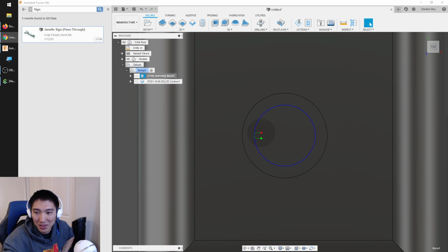Can you use grinding bits in the Nomad? Technically, you can, but you'd have to feed really slowly because you can't trust that. Like when you use a Dremel, you can't just plow through granite or whatever it is you're carving really quickly. So your feed rate's going to be super low. And depending on what you're grinding, you really want to use some sort of dust collection or a little water drop system just to keep abrasive dust from getting in the bearings and electronics.